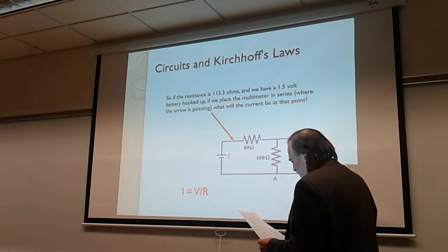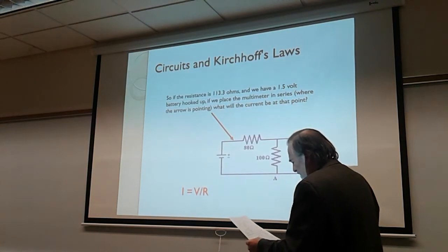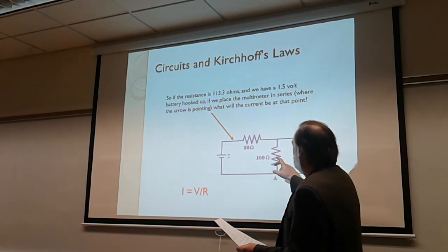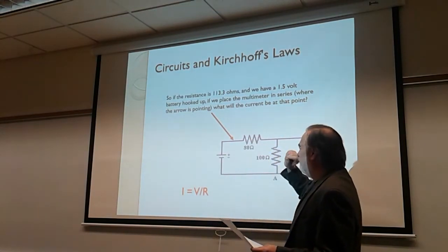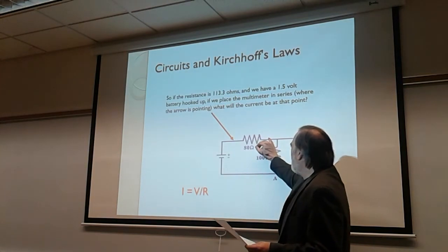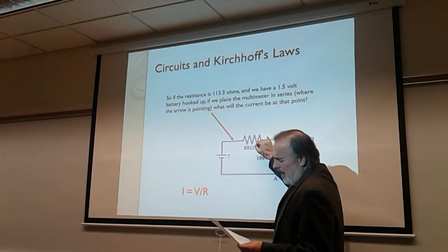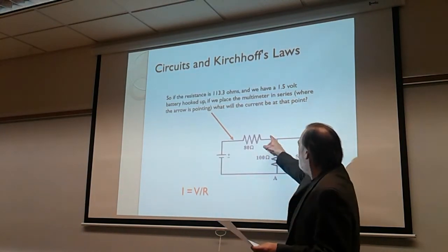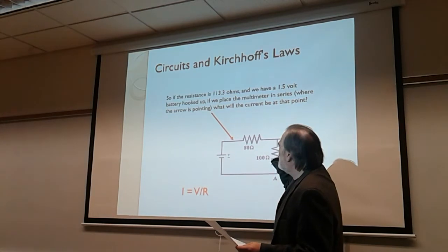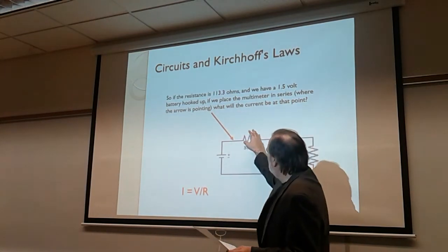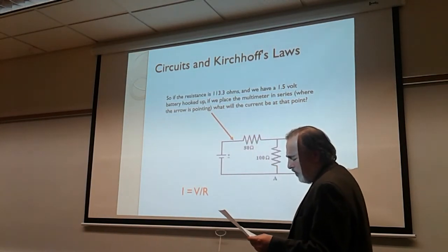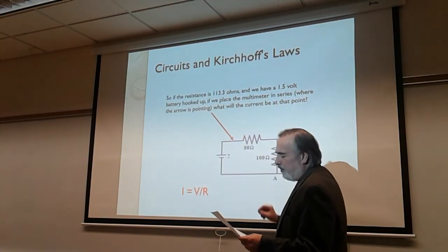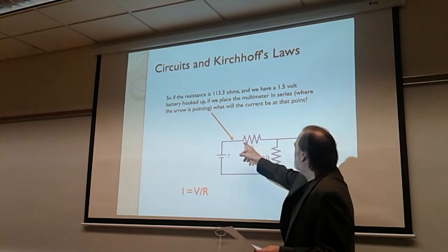And taking that voltage drop, about 1.056 volts dropped by that resistor, we come out of it at this point at roughly about 0.444 volts. Still have the same current. Current's the same in that series portion. The current being, of course, what we calculated before as 13.2 milliamps.